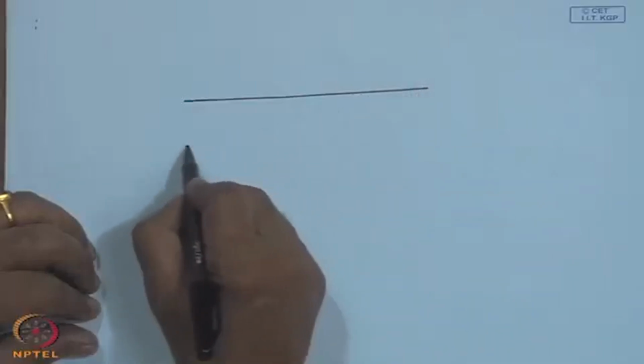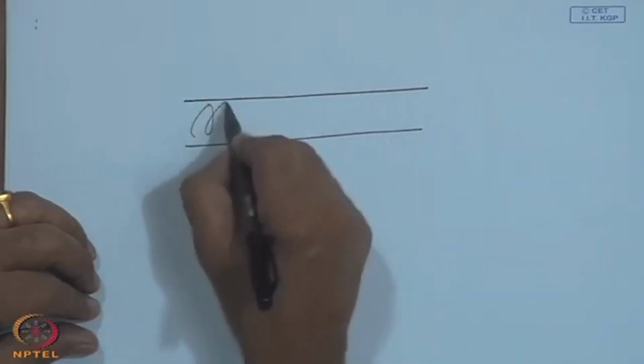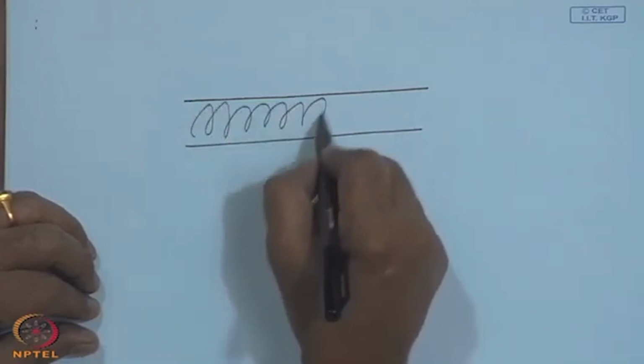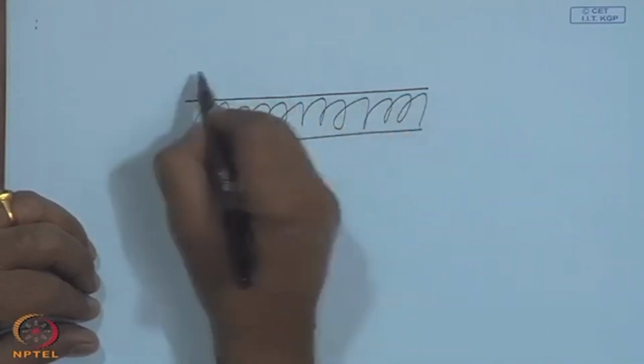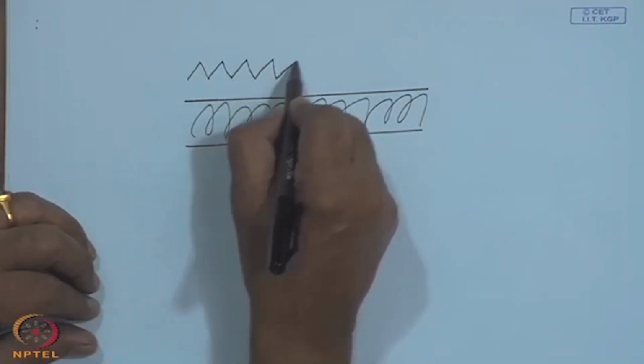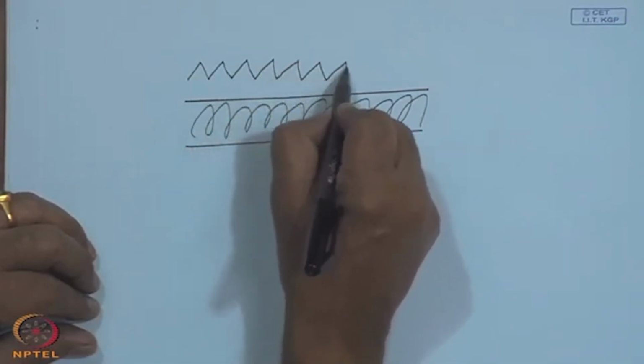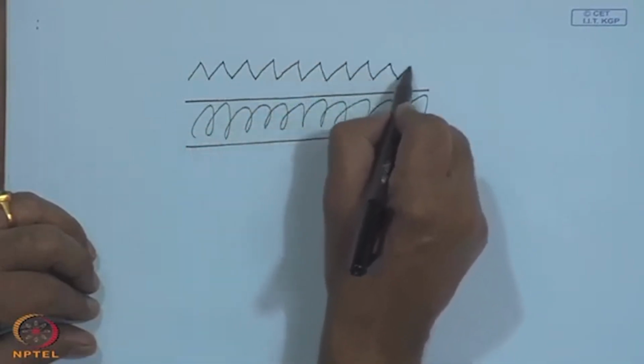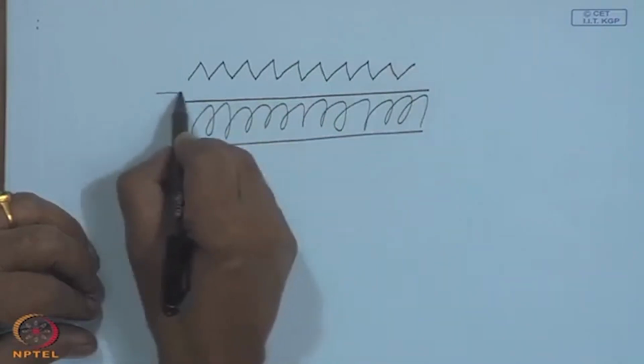Then once again the whole game has been to improve the heat transfer coefficient, and improve of course the absorptivity. So, people came out with, instead of these fins, a corrugated sheet absorber, and the flow is in this direction.